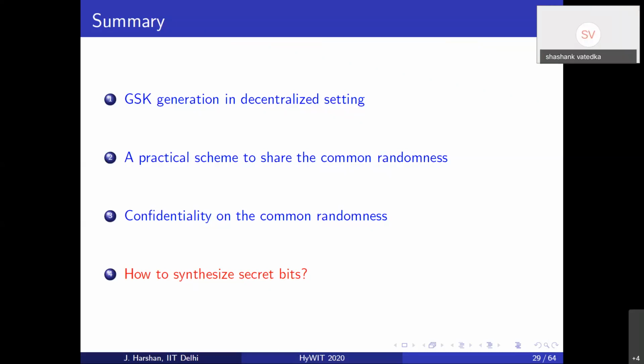Yeah, and also independence across users is important because you're broadcasting the sum. So I suppose you will require the sum to be independent of the individual H_ij. That's right. When we go back to pen and paper and compute the mutual information with respect to the eavesdropper, we would need these assumptions to prove that its mutual information is zero. In fact, what we have shown is they will have to be identically distributed. So it's not just independent, they also have to be identical in order to prove the results. But I'm not sure if we have given a thought on what would happen if they are not identical. Maybe I'll have to come back on that later. So don't you need uniformity at some point? If the points you're transmitting are uniformly distributed across the points.